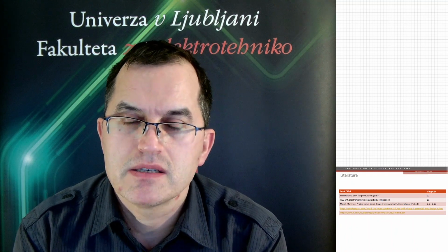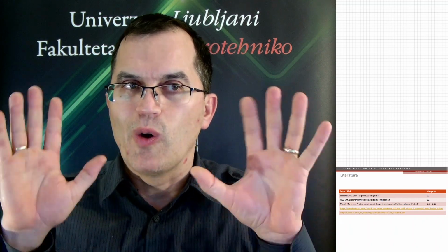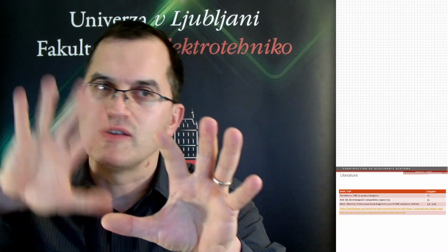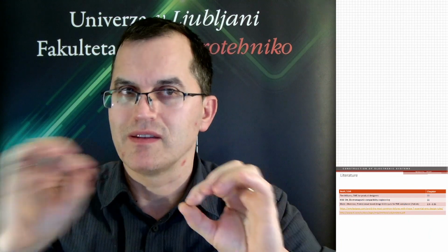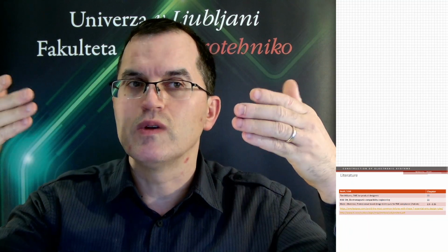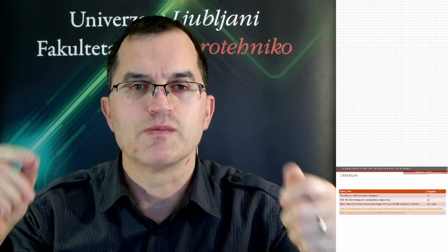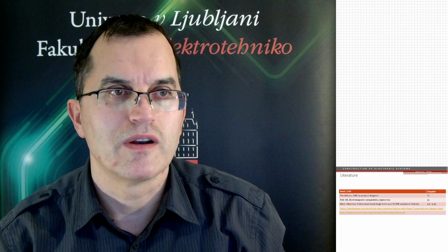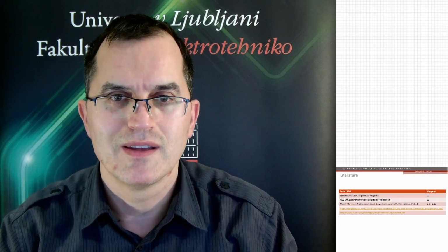And to conclude this lecture about ground planes and split ground planes and signal grounding in general, you should be careful when you are splitting grounds, because what you do when you split grounds, you always increase the impedance between two grounds. And if you increase the impedance between them, then you have to make sure that there is no high-speed current flowing through that part of your ground. Because if it does, then you will increase the voltage difference between these two grounds. And that's not good. Because if you connect cables to it, then you get so-called common mode generation, or current-generated common mode interference.